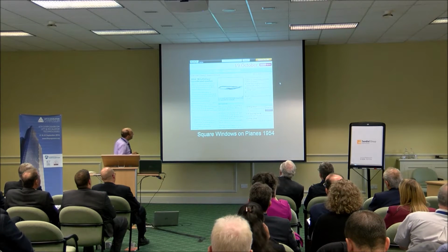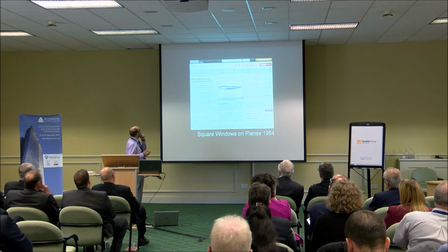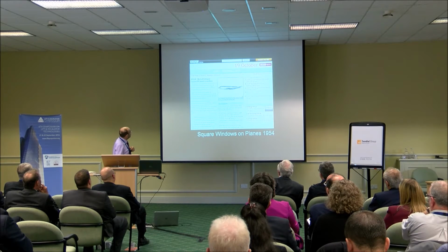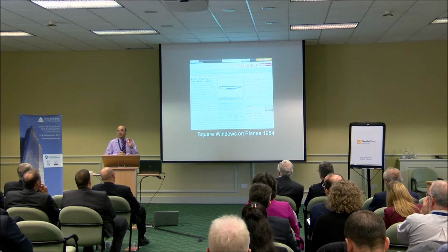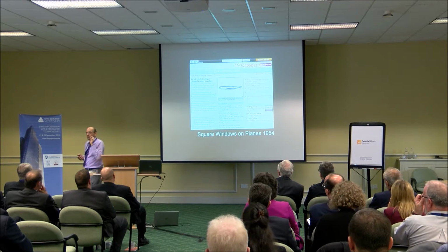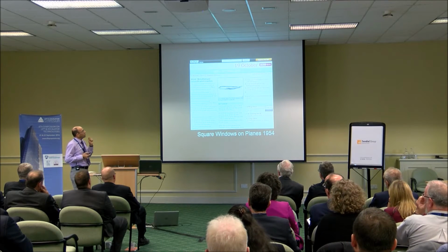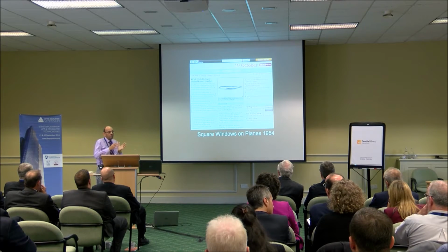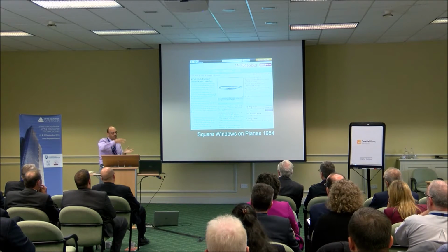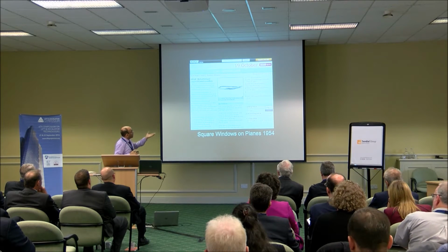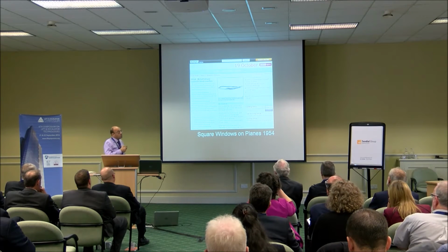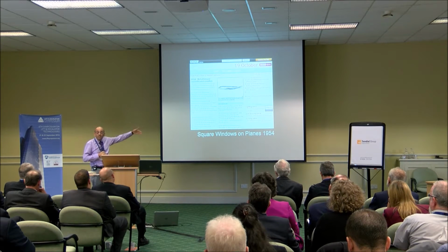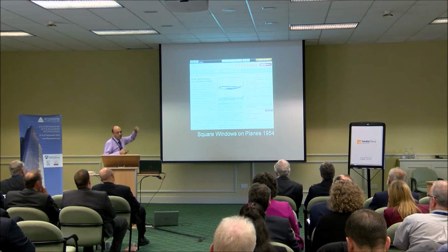Another good example, actually, metal fatigue. This is the Comet, 1954, two fatal crashes, and it turned out the square windows were a problem, because a square window would actually be a stress concentration point. It increases the stress so much that it initiates a crack, and then the crack grows through fatigue, because every time you pressurize the cabin and depressurize it, that's a cycle, and then you get quite fatal results. So that's another iterative theory and practice cycle.